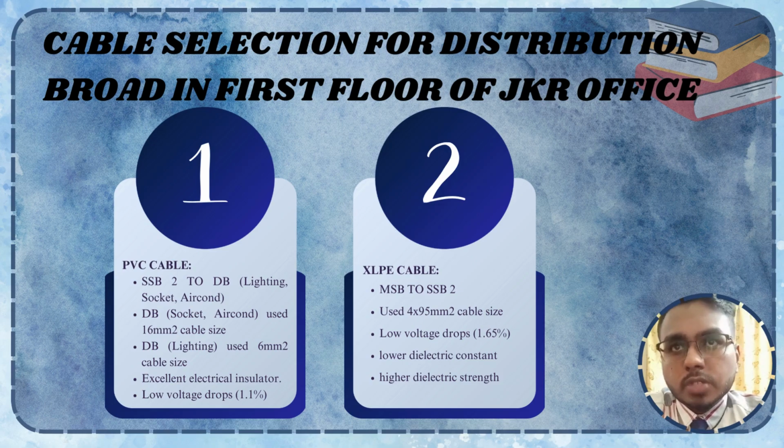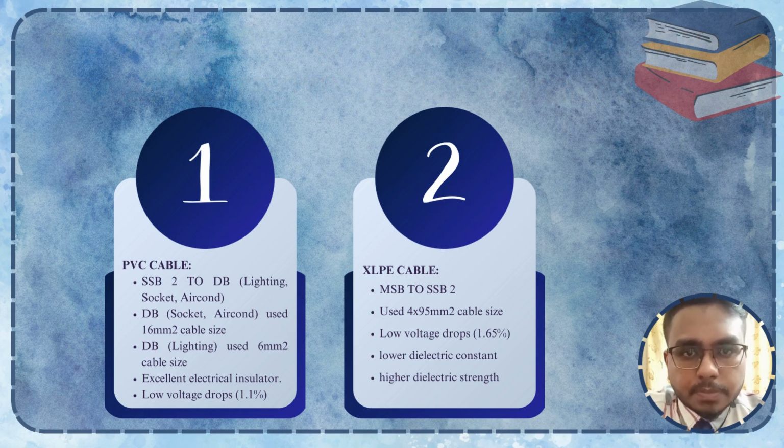Furthermore, in comparison to traditional PVC insulation, the improved electrical performance of XLPE insulation offers superior electrical qualities, such as lower dielectric constant and stronger dielectric strength. This results in improved overall electrical performance of the cable, making it a superior choice for varying demanding applications.